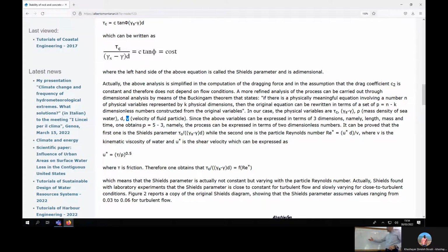And then there was a minimum value of the shear number. And then for increasing turbulence, increasing velocities, he found that the equilibrium conditions were reached for a quite constant value of the shear number, and this constant value is 0.056, more or less. Some authors say 0.047. The original result of Shields was 0.056, but then some authors corrected it. Just focus on the concept.